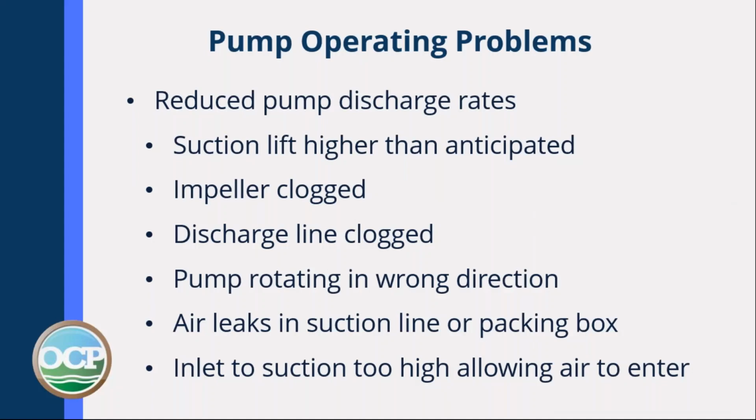Make sure the suction lift is not higher than you anticipated. Make sure the impeller is not clogged. The discharge line could be clogged. If the pump was recently put back in service, make sure it's rotating the proper direction.